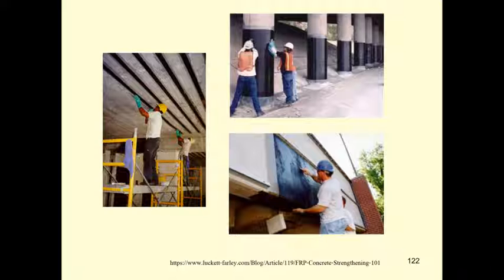And it's also used in many ways. For this one, the FRP, the back one, is used for what's called strengthening. This is going to be an RC column. In the past, there were some earthquakes that hit, like in Japan and in the US, and some columns may get the earthquake force and have some damage. So you can strengthen the column by this. Or this one is strengthening for the beam. You can put the FRP, the back one, on the bottom.